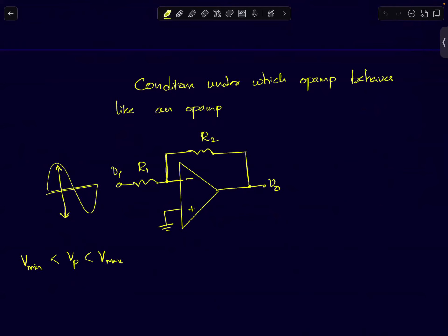If you have an op-amp based circuit, so far we took an example about the saturating nonlinearities. And we said, okay, there is a limitation on the peak voltage you can apply. If I tell you that the output voltage cannot go greater than plus minus VSAT, can you tell me in this circuit, what is the maximum input signal level that I can apply and expect faithful amplification?